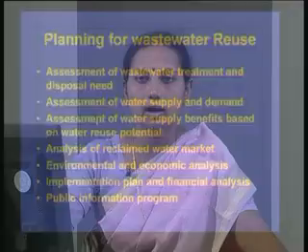Though the technologies are available, or many technologies are feasible, even now wastewater reuse, especially for drinking water or domestic purposes, is not gaining much attention, because the cost involved is very high and public awareness is very important for this purpose. So now we will conclude whatever we have seen today. We were discussing the dissolved oxygen model. Using that model we can get the dissolved oxygen profile of the stream, and we will be able to find out the maximum deficit and the location where it is occurring. Based upon this we can manage the wastewater discharge into the stream.